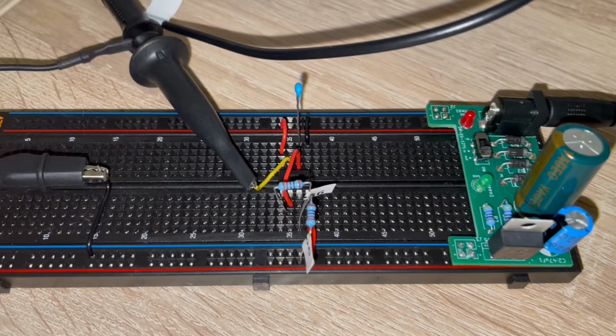And of course, we want to do this circuit now in practice. Just before I say it's really magic, I take a 1K resistor, it's your average off-the-shelf resistor, and you take another 1K resistor, your average off-the-shelf resistor, and then you take a 100 nanofarad capacitor, you have that lying around, and you just put that together and it swings with 4.8 kilohertz. And now let's go to the bench and do that.